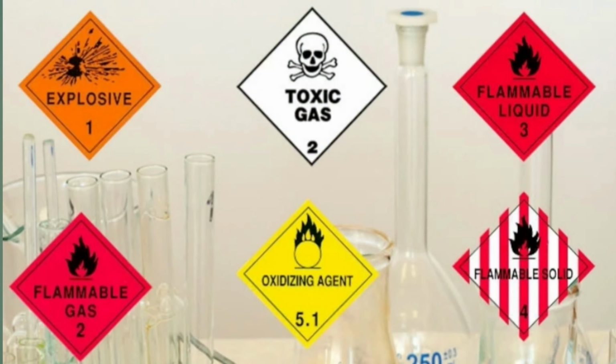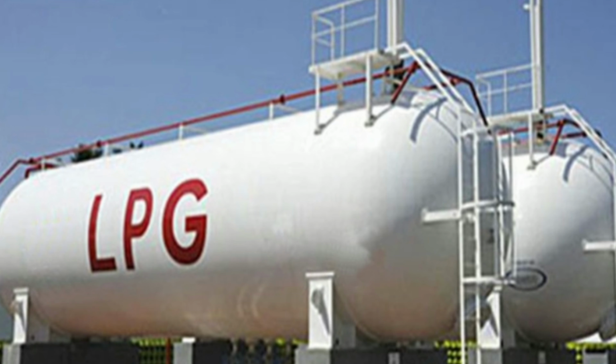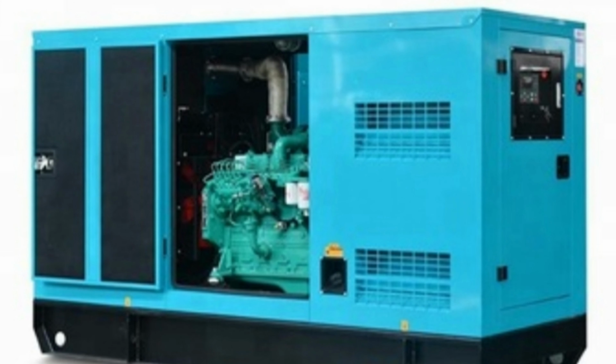Hazardous substances, in particular gases and vapors. Excavations will fill with any gas that is heavier than air, such as LPG and carbon dioxide. Adjacent combustion engines, such as generators and compressors, can act as a source of exhaust fumes.